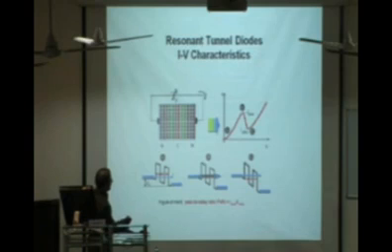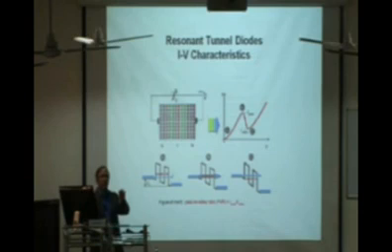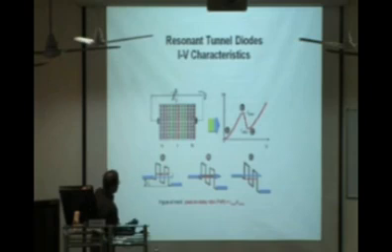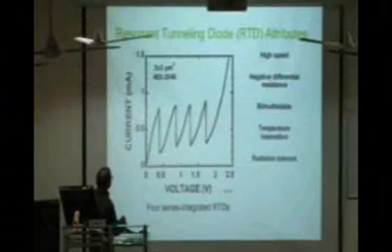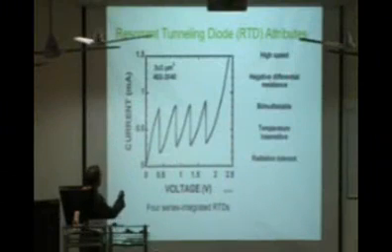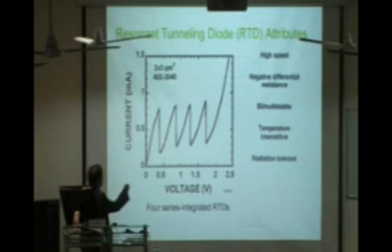Ideally, if you can really confine many states within this quantum well, there's a real challenge to get a number of states quantized in a quantum well. If you have three or four quantum states instead of one, ideally you should get a current voltage characteristic like this. This will be when it's resonant to the first ground state, the second quantized state, third quantized state, fourth quantized state.